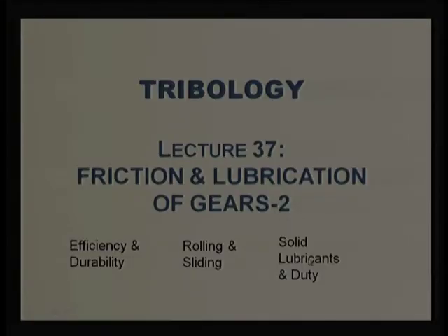Then we discussed something about solid lubricants. We can use a solid lubricant like nylon or other polymers. We can make gears directly from polymers, and then we do not require extra lubrication, but it depends on whether the application is light duty, medium duty or heavy duty.